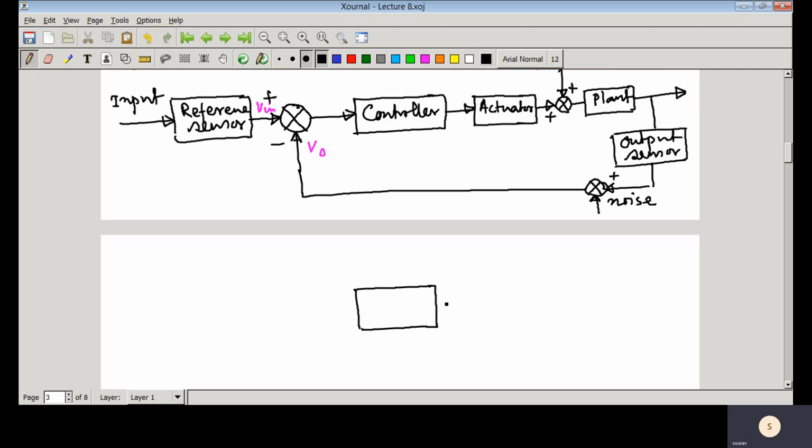In the block diagram that you have seen in this particular diagram, the block diagram is basically an input output representation, and in case of nonlinear system, as the Laplace transform, the transfer function concept does not hold, so in that case we just represent that block in time domain, that is say input u(t) and output y(t), and g is the nonlinearity.